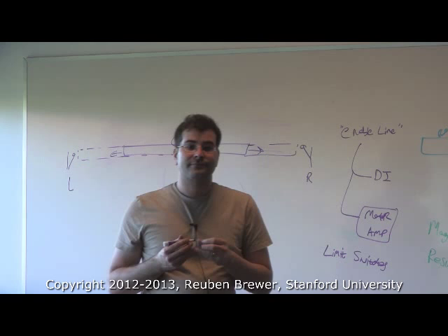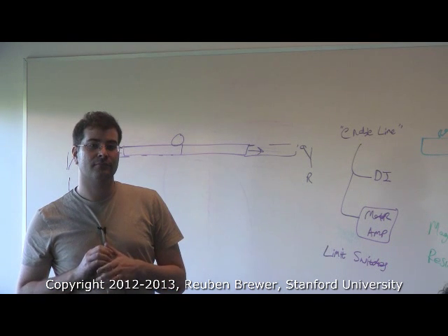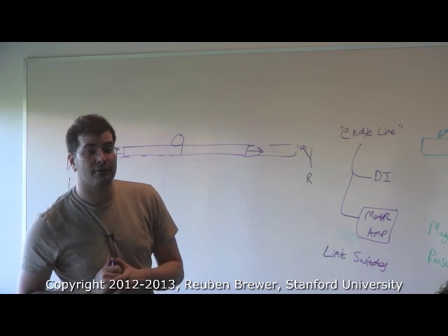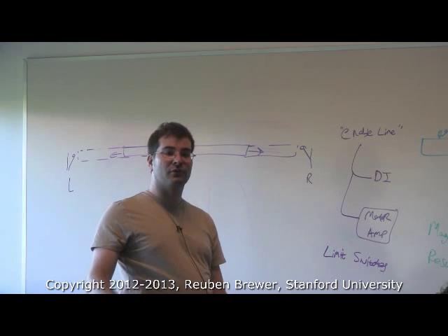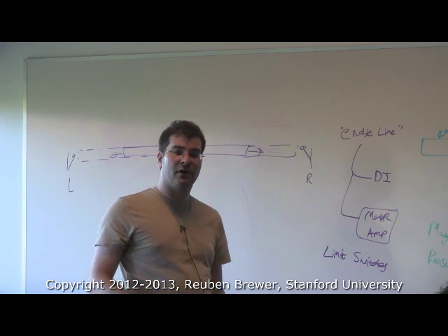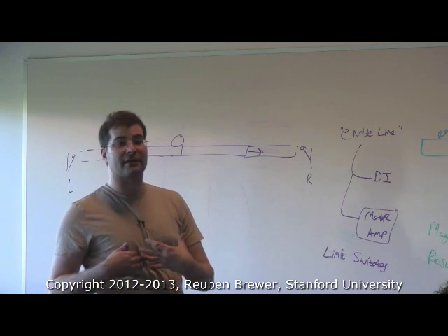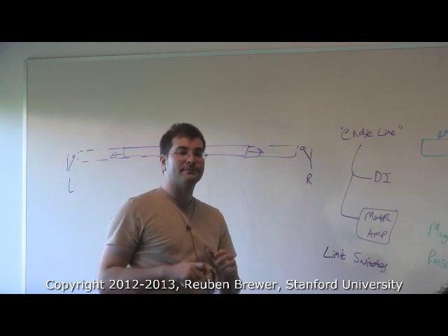Maxon, yeah? For the enable line that you were talking about with the button, why would you put it into the motor amp instead of the button, like open up a switch or something? I would put it into both. For me, I want soft stops and I want nuclear war stops. The soft stops are for when my code spazzed, but no one's in danger. So I do IV robotics. For my robot, you stick your arm in and it pokes you with a needle.